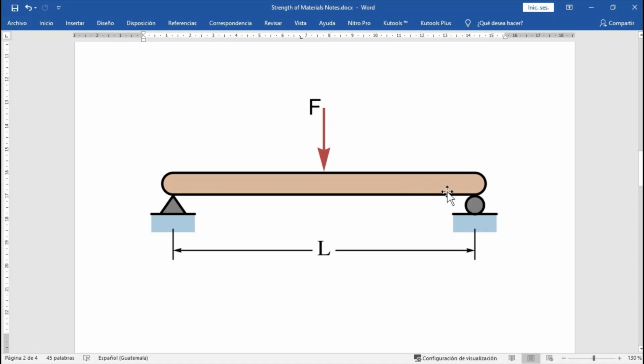But horizontally it can roll, right? So you can displace the beam in this side. So these are two types of supports, right? And the supports create reactions. For example, here, as I told you, this one will create a vertical and a horizontal reaction. And the circle will create only a vertical reaction, okay?